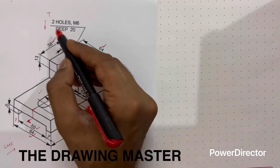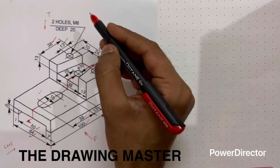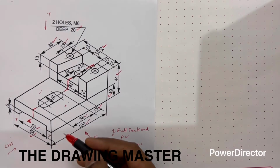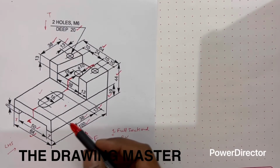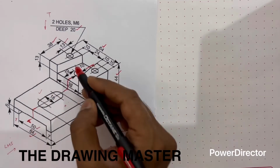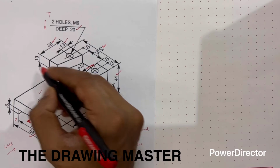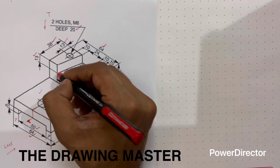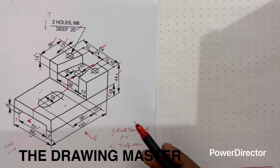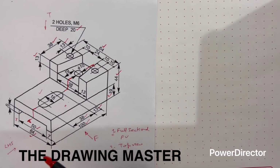Here it is given that 2 holes M6, deep 20. Right? Now the next part is 13. Yes, this depth is 13 mm. Now any other dimension? We have now read all the dimensions here. So let's start to prepare the drawing.